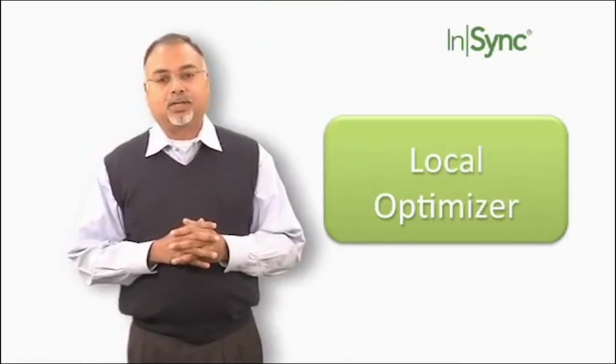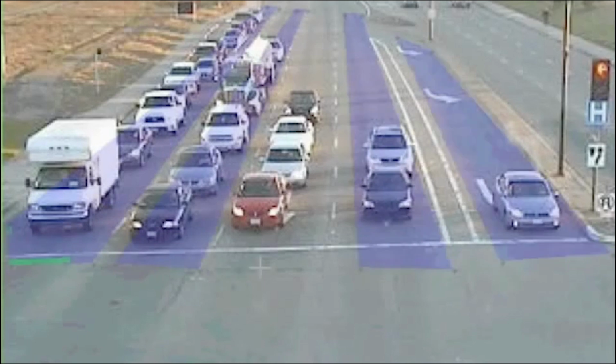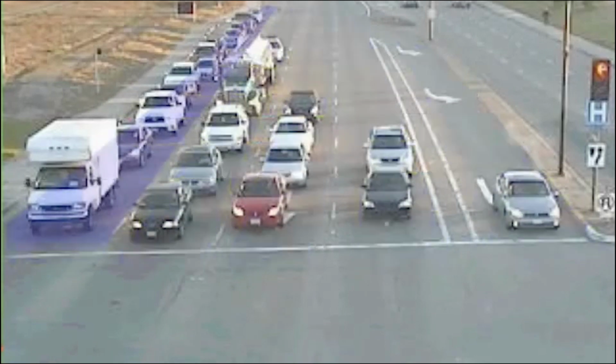Let's look at the local optimizer. So in our system, we have a camera that is facing every approach. And these cameras determine the queue length at every lane. As cars approach in, it recognizes the cars, and we keep a running count of how many cars are waiting at the intersection. Now, the way we do that is that we draw detection zone along the contour of the lane as far as the eye can see. Then we subdivide those detection zones into segments, which are approximately the length of a car. And we count the number of segments, and therefore we get the number of cars that are waiting.